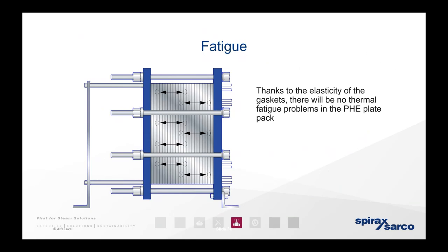So fatigue, when we talk about fatigue with plating frames. So thanks to the elasticity of the gaskets, as it says here, there will be no thermal fatigue problems in the PHE. So that's plate heat exchanger, plate pack. So yeah, the expansion, the retraction, things like that, the gaskets are designed to take that stress.